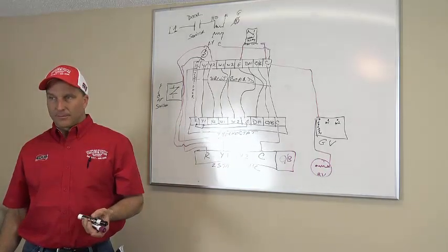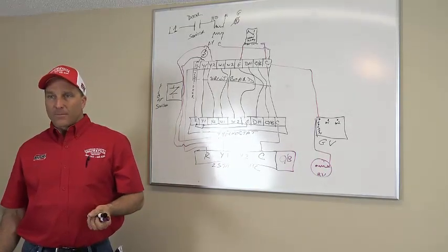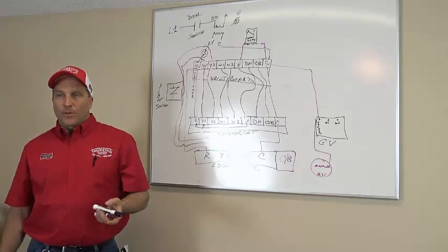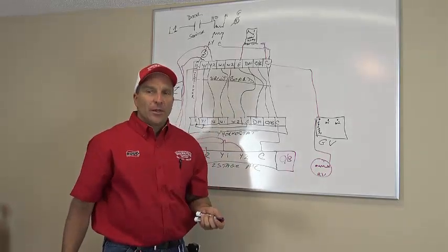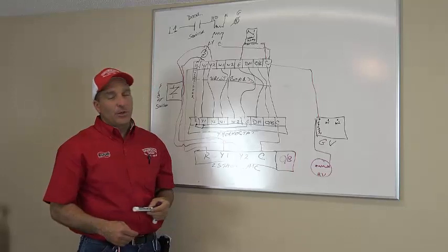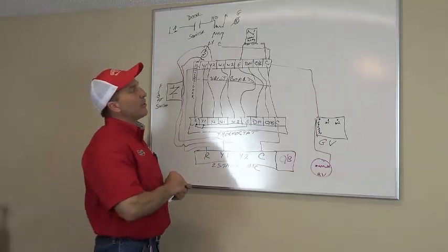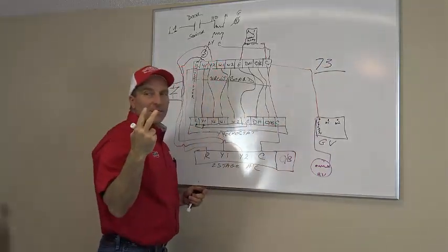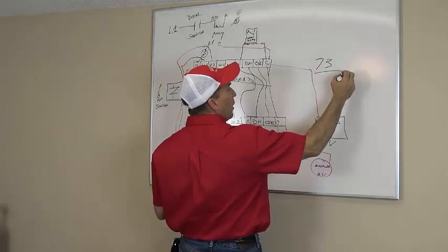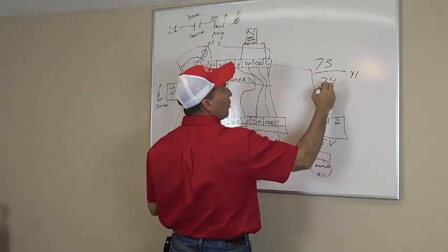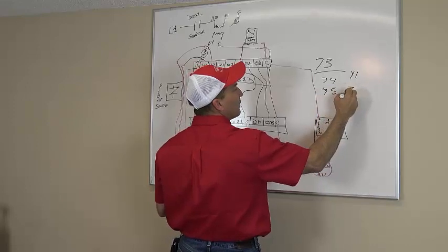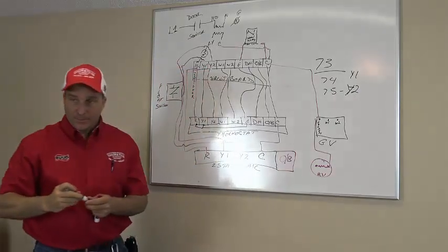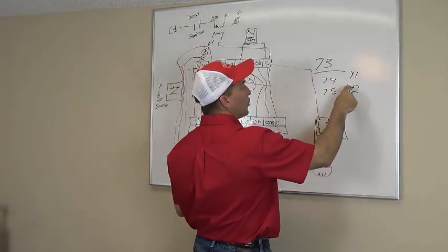Below 3 degrees. When the thermistor reads that it's way hotter outside than inside. No. Your thermostat kicks on Y2. There's normally a 2-degree differential. So if you set your thermostat at 73 degrees, for an example, on a 2-stage thermostat, okay, Y1 will kick in at 74, Y2 at 75. Okay? 2-degree differential.